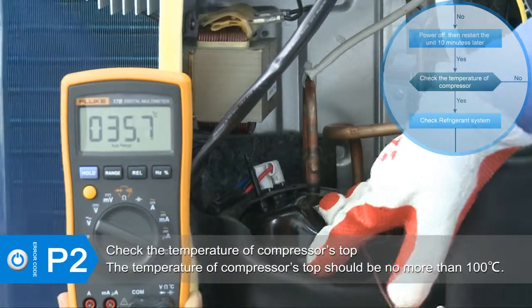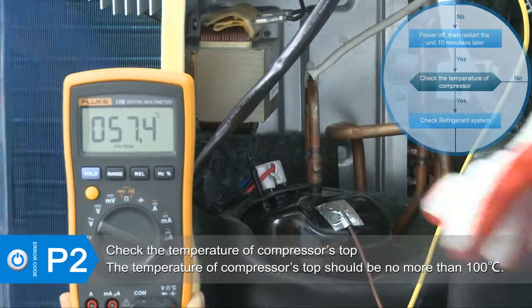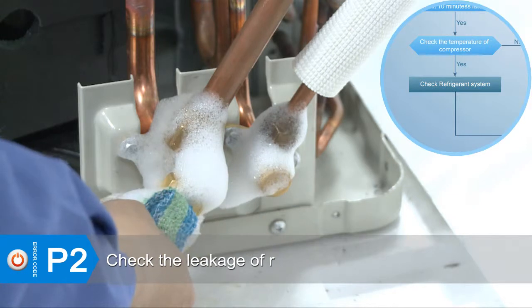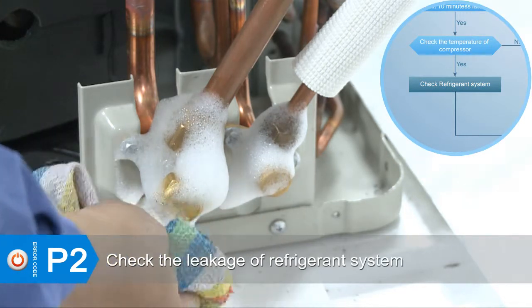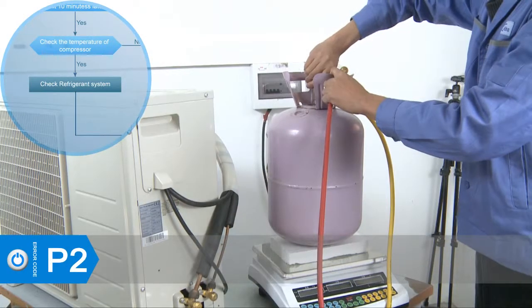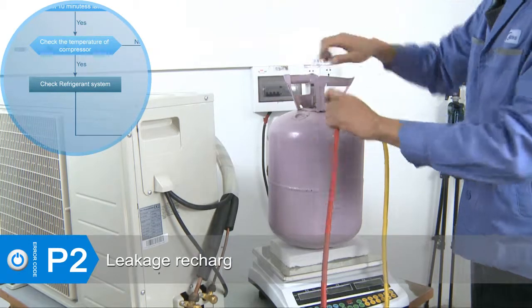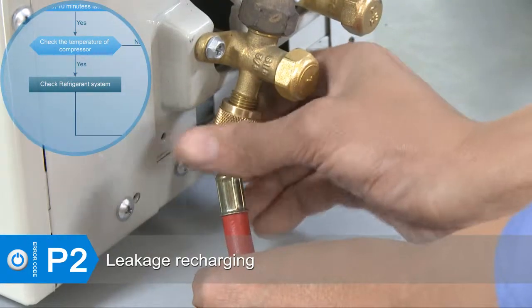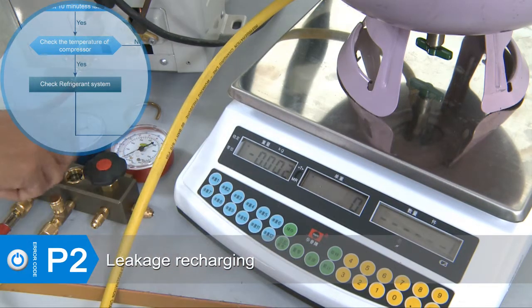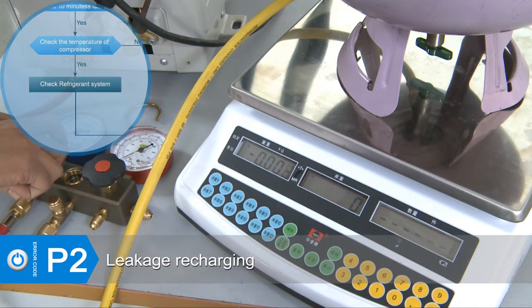If the temperature of the compressor's top is higher than 100 degrees Celsius, it could be a refrigeration error. If there is refrigerant oil on the joint, apply soapy water or leak detector to check if there is any leakage of the system. If there is any leakage in the system, repair the leakage, then vacuum and recharge the refrigerant. If the refrigeration system is blocked, replace the high-pressure valve.